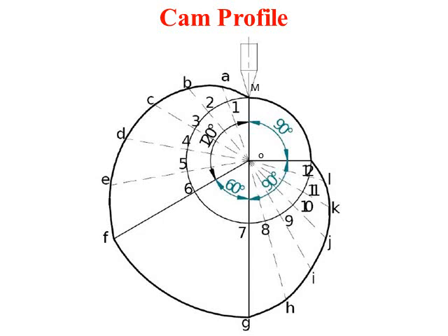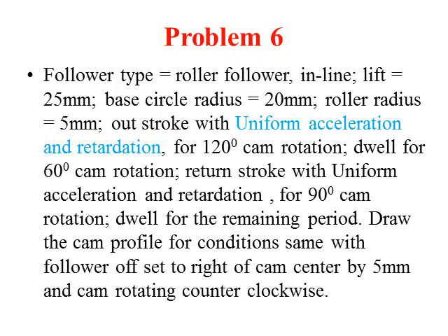In the same way, transfer all the values from the displacement diagram to the cam profile. After marking and transferring all the points, join all the points, that is A, B, C, D up to L, with a smooth curve. So that will be the cam profile when it is inline. So that completes the problem. Next problem.